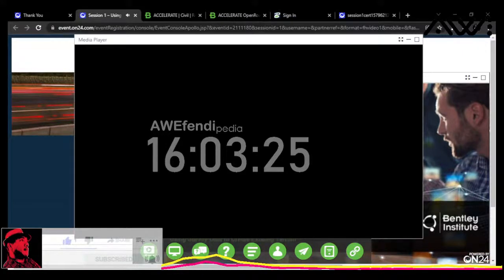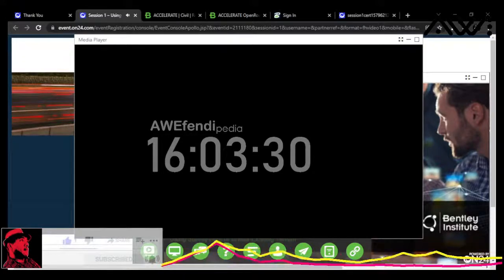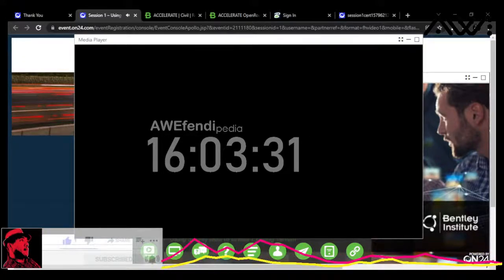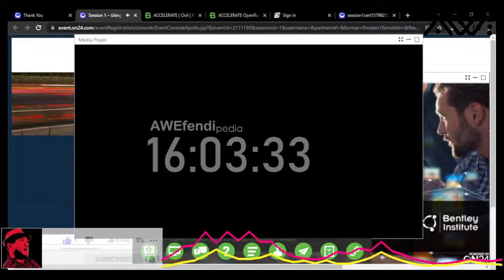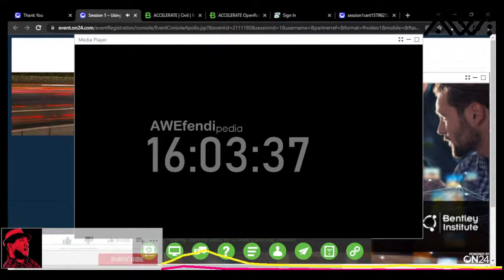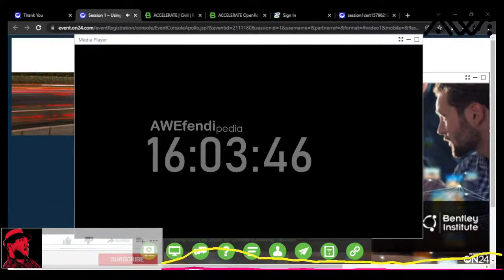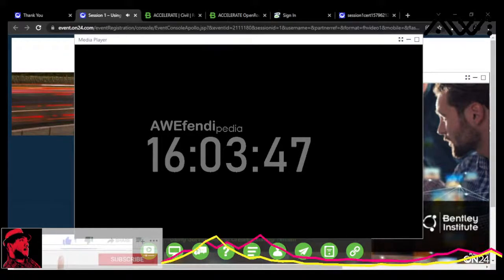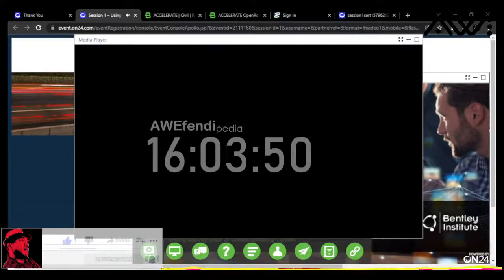So what I'm going to do next, I have my field book ready. I have my settings ready. Let's go ahead and import that text control file. So I'm going to go back here. I'm in the Explorer again. I'm going to go back to the survey tab, and I'm going to right-click on my field book that I created, and I'm going to choose the import option, and I'm going to import a file. And the first file I'm going to import is just this control file.